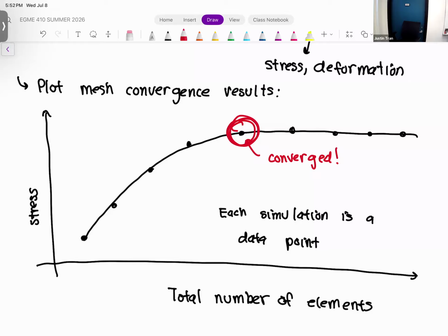Okay, so if the nodes were shifted, and we were to make a skewed element, those would be closer together. And skewing is that. So skewing is bad mostly because of how it computes the derivative. When we have a skewed element, the lengths between the different nodes are imbalanced, so you may have one that's really short or one that's really long. Because the lengths are uneven, you're not going to get an accurate computation of the derivative.